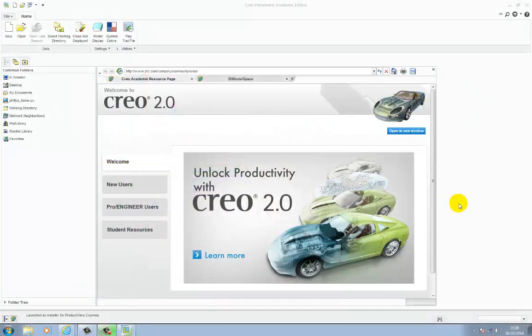Engineering drawings in Creo 2.0. This video will concentrate on drawing the format for an engineering drawing. The format is the outside border plus the cells for the title block. We will then do a second video that will show you how to put the text into the title block and also import your logo.